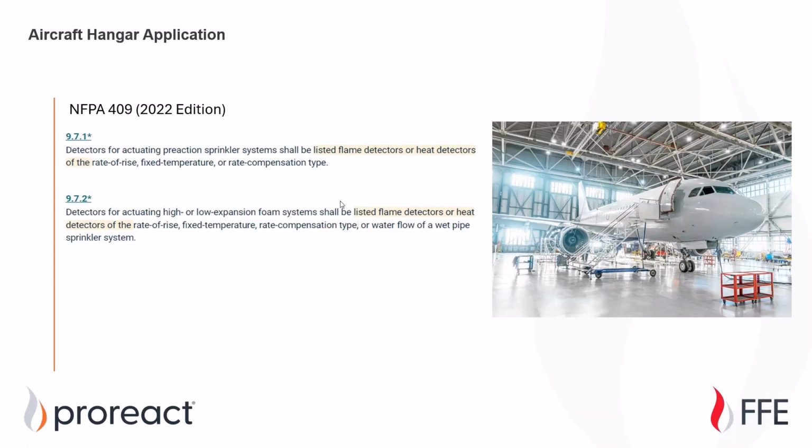Another popular application for linear heat detection are your aircraft hangars. NFPA 409 is the standard for that one. They mention heat detectors, fixed temperature, rate of rise, or rate compensation type. We offer the fixed temperature. And also it mentions flame detectors.